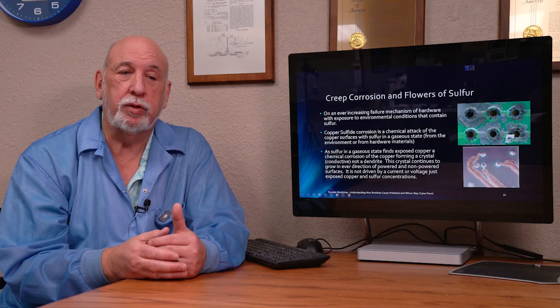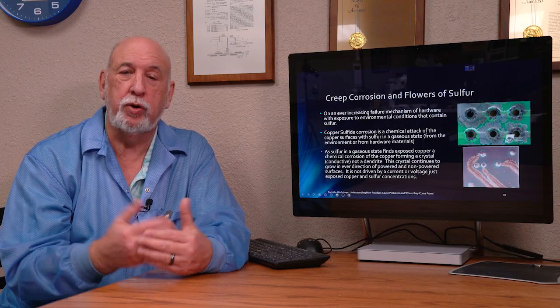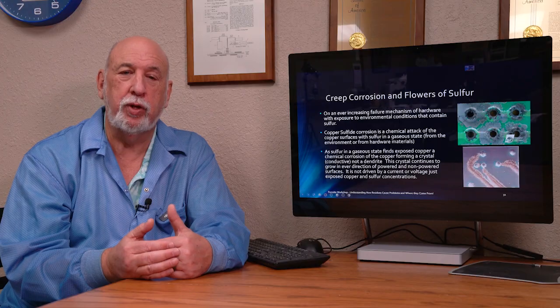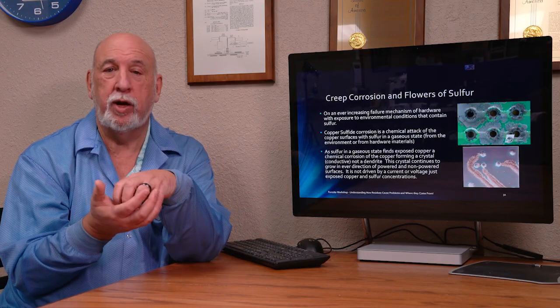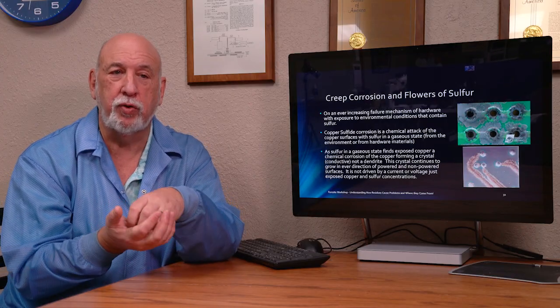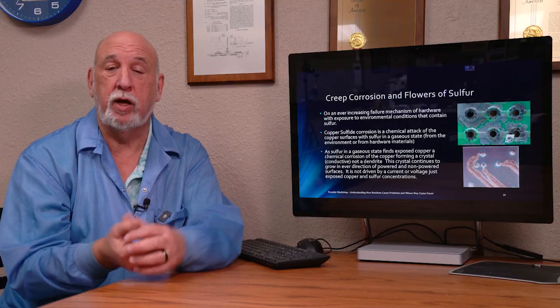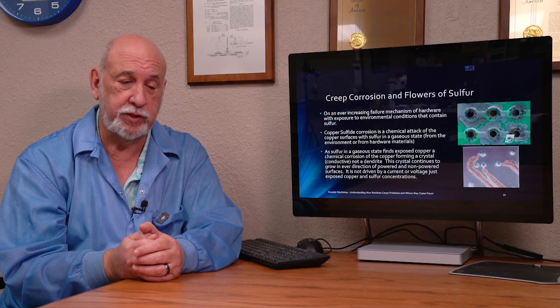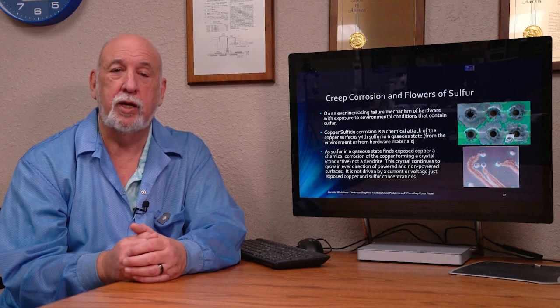The silver will pit and change. The indium will corrode, and typically in an LED we'll have an indium layer with a wire bond over the top of that, so it'll create an interface issue, and the wire bond will lift on the indium interface. The silver will corrode and short internally.